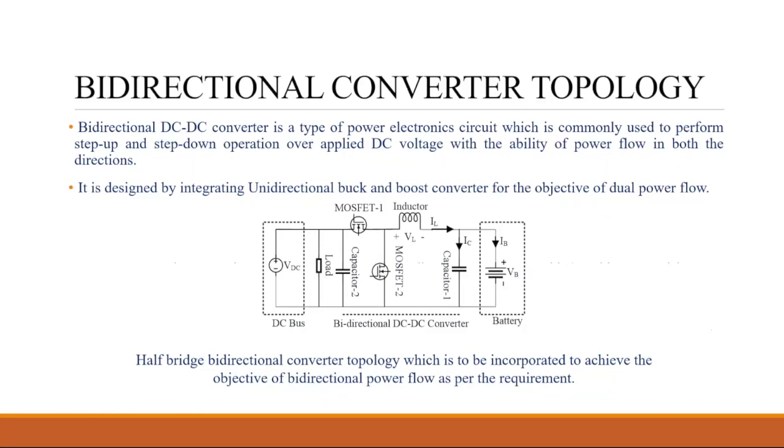And similarly, what is a boost converter? This is a buck converter, and this is what a boost converter is. There is an energy storage element. This is a switch. There is a freewheeling diode, and there is a capacitor for filtering. Okay. Look at this circuit from this side. Source, inductor, it's a boost converter.